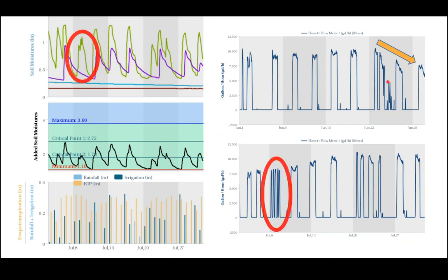In a desperate attempt to solve it, he did pulse irrigation and ran it four times a day, which doesn't really help because those pulse irrigations keep the water shallow, not deeper. We ended up finding that the flushing valve was stuck open. So he was losing a good percentage of his water through the flushing valve, like 30 to 40% of the water was going back into the reservoir.